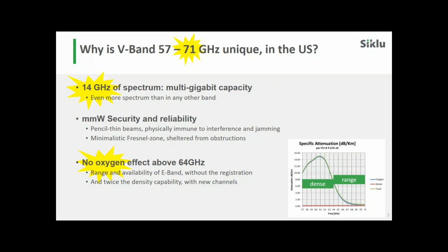However, if the power supplies that you want to use are not PoE capable, it is also possible to utilize a direct DC, and we have two options to do that in the 614, just as we have in the 600TX. The first option, if you only need 2 ports out of the radio, you can plug a direct DC into ETH-1. We have a small accessory where you wire your two wires into a special plug, and then that plug has an RJ45 male connector on the other side and connects into ETH-1. As long as you do not need more than 2 ports on the switch, that is a perfect solution.